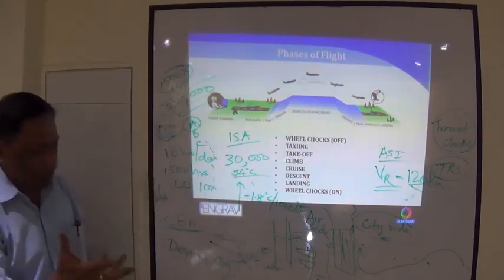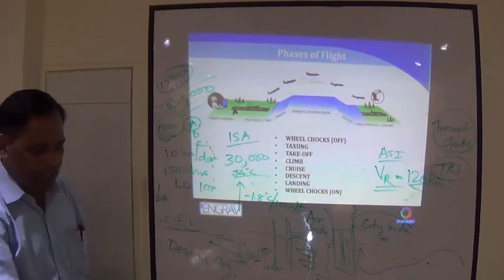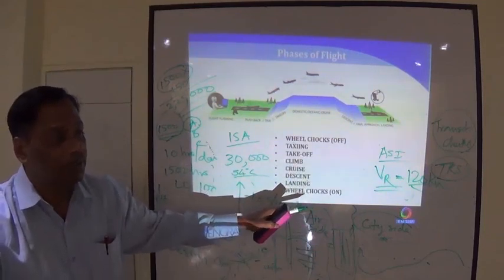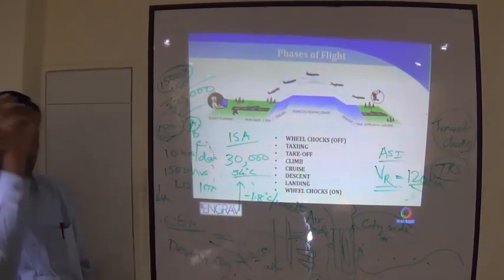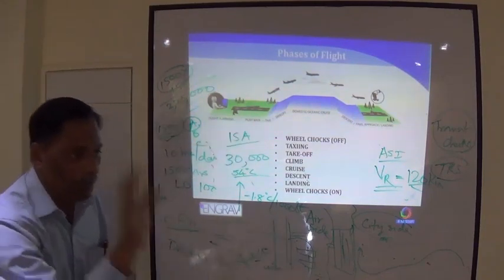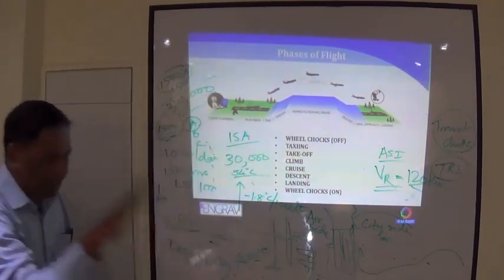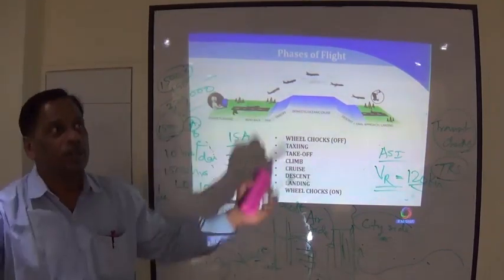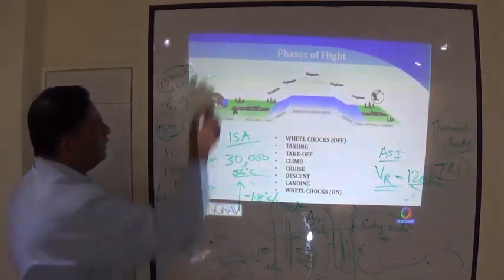For an aircraft fire or oil fire, if you use the normal fire tender with water, the fire spreads. So what you do is you use a crash fire tender, which pumps out foam. This foam sits over the aircraft body as well as the fuel and oil, and it cuts off the oxygen supply. Fire is a fire triangle.